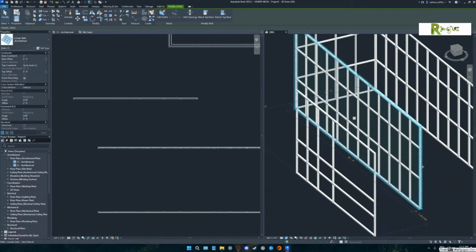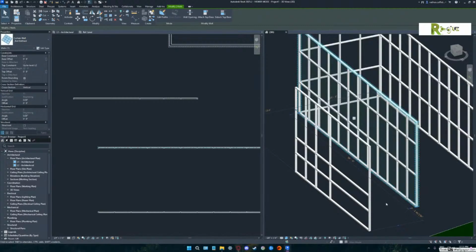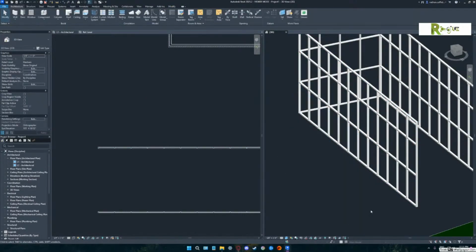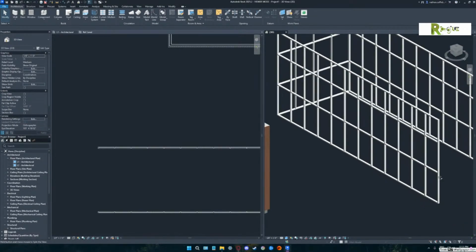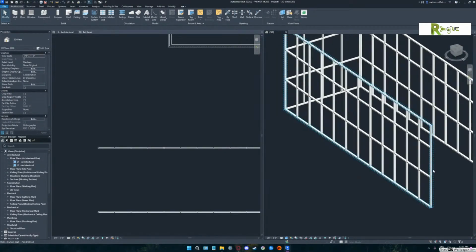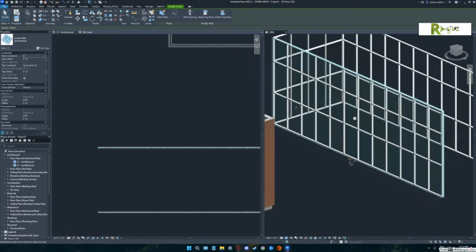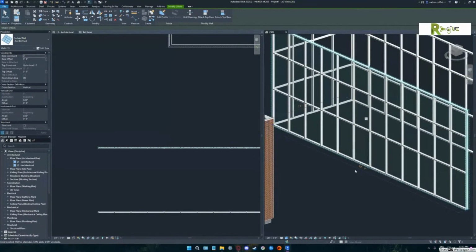Correct. And let's take the one that we built separately and delete it out of our way so we can see the stuff behind it. You just need to grab that container. It's a wall. So if you remember, we were trying to put in that double door, but we didn't really have enough distance for that double door. So I want you to select one of those vertical grid lines. When I say grid line, hover over a mullion, tab till you see the grid line. That's it. That one. Perfect.